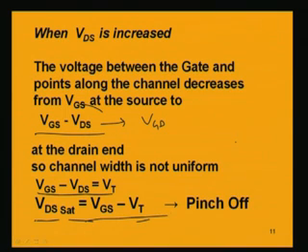So, the voltage between the drain to source which causes that pinch off, that means the saturation, that voltage is known as the saturation VDS, the VDS sat, and that is given by VGS minus threshold voltage. And what happens then? Then the drain to source current becomes saturated, and if you go on increasing VDS beyond that value, then it will continue to be in saturation, there will be no change. That is, the drain to source current becomes maximum at that saturation point VDS sat when this condition is met.